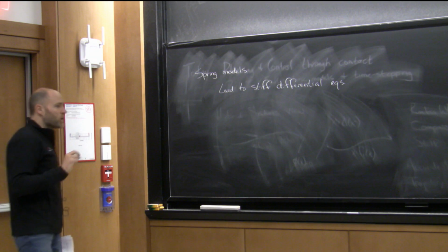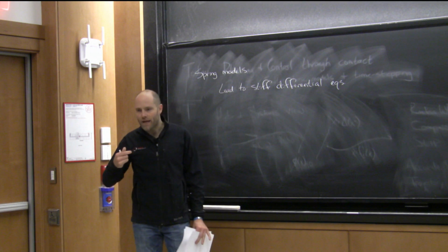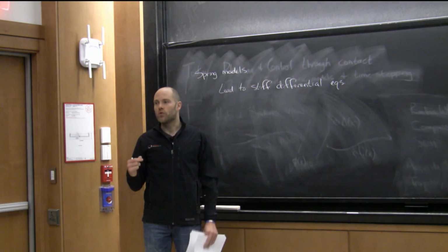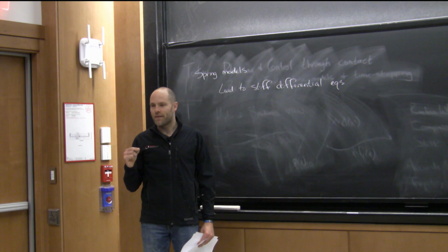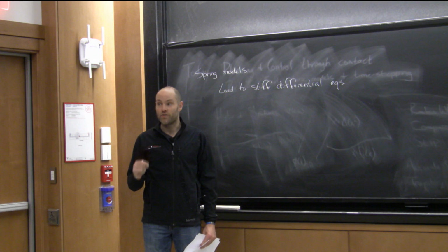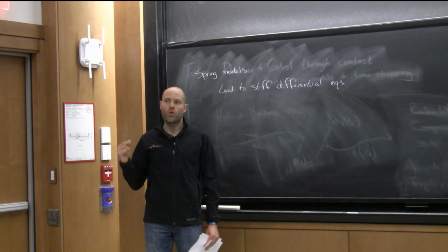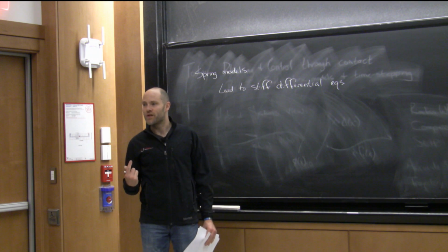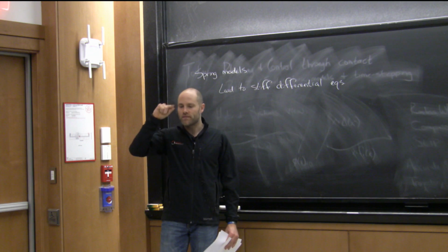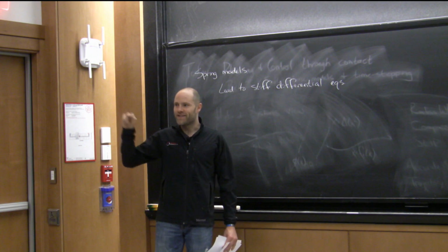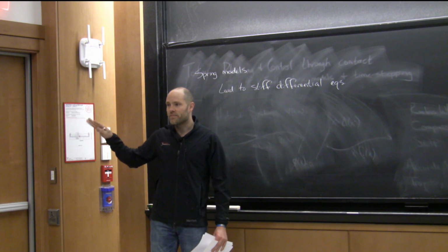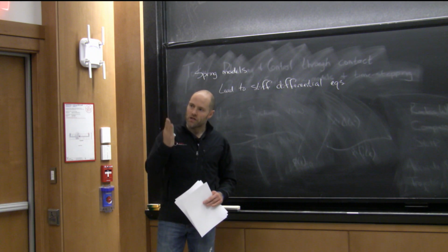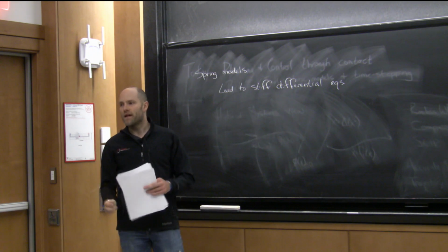A stiff differential equation is one where the characteristic timescales change a lot across variables or across time. So basically, you have some numbers that are coming out really big and some numbers that are coming out really small. If my mass is on order 1, and then my spring constant is on order 10,000 in order to avoid penetration, then the differential equations x dot 1 might have order 1, and then x dot 3 might have order 10,000, and any method that's based on a gradient-based estimation of the integral will start being confused by that and have to slow down.